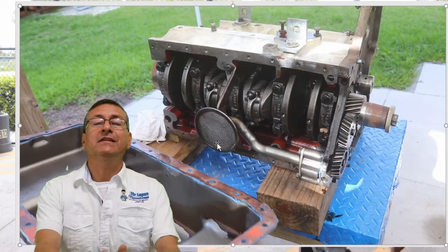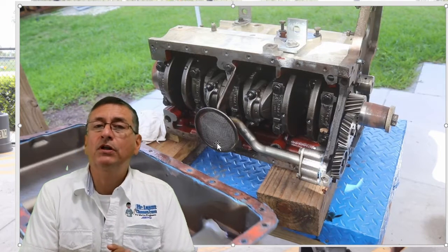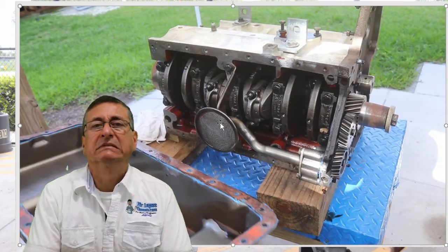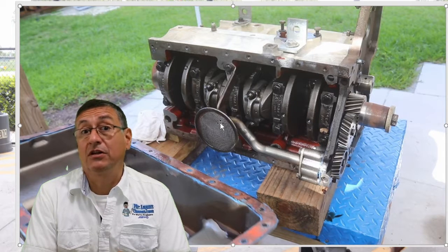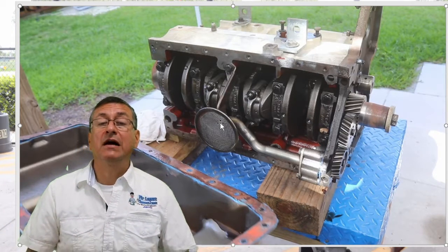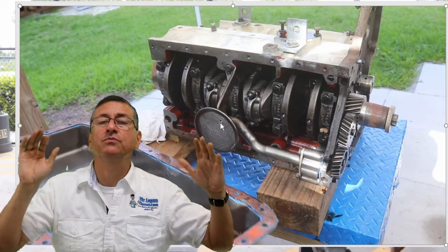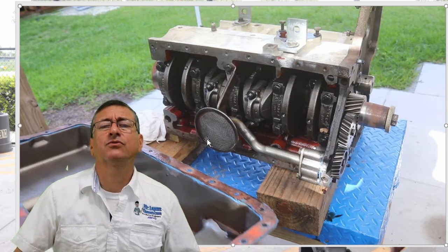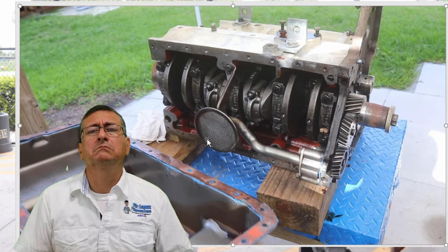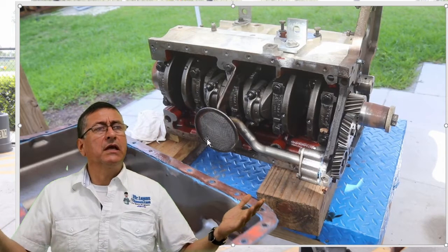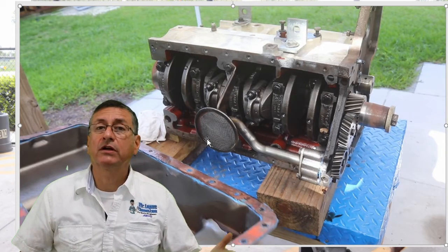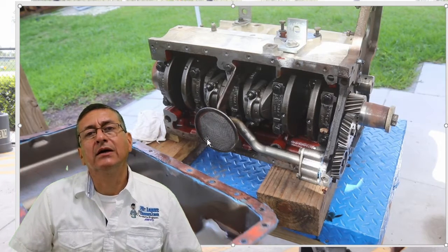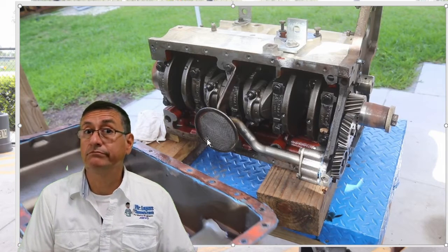This strainer is an important element. Because what happens if this strainer is clogged? The circulation of the oil is not enough, and you have a lack of lubrication, and you have millions of problems internally on the engine. How can that strainer, that filter, be clogged? If I replace the oil according to the manufacturer recommendations, and suddenly that strainer is clogged, there are different possibilities.